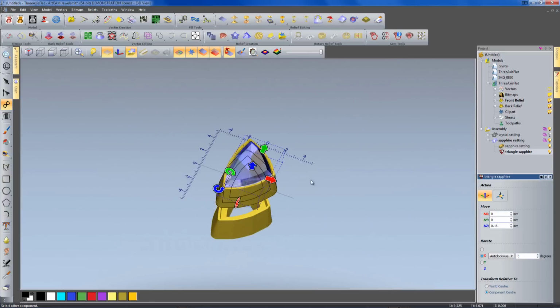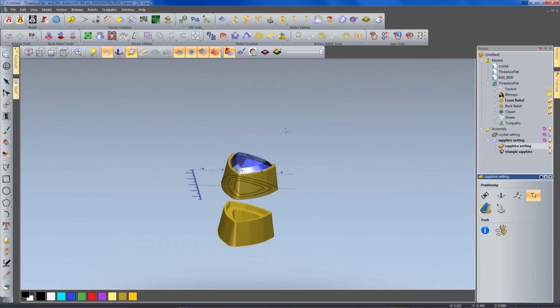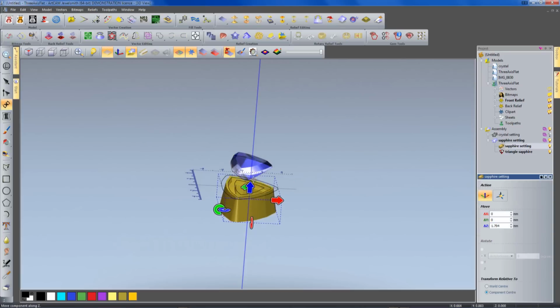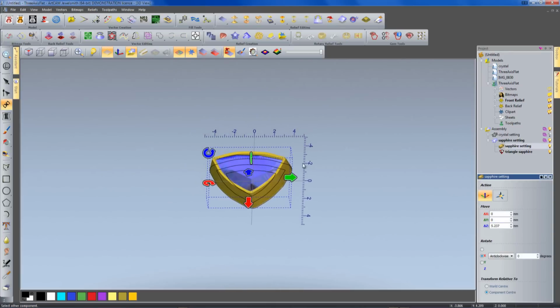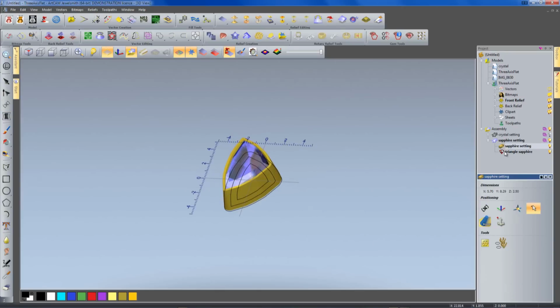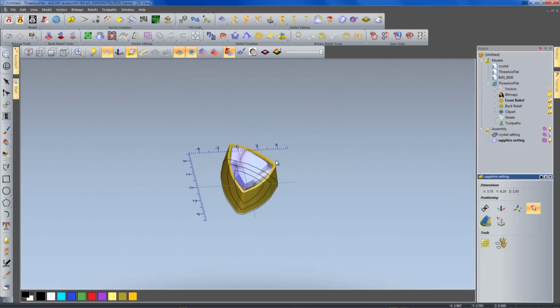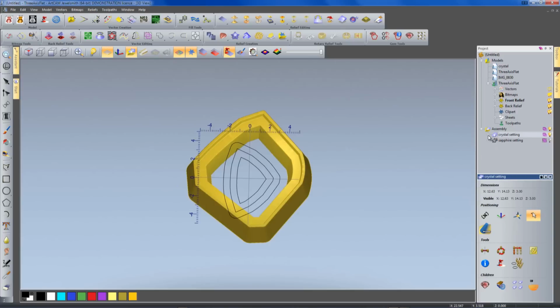I just need to turn off the relief model because I'm still building that here as far as ArtCAM is concerned. So if we just turn those layers off at the top of the screen, and now we can see the actual STL model. I'm going to transform this one, just drag that up into place so you can see that's okay. And that's ready to go now, that's all together. Now, we've got some new options inside the assembly folder here. These ones will lock all those items inside. They group things together, so when you move them in the assembly, they'll stay together as you move them.